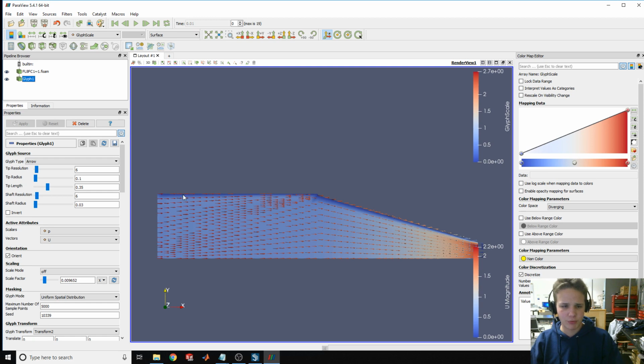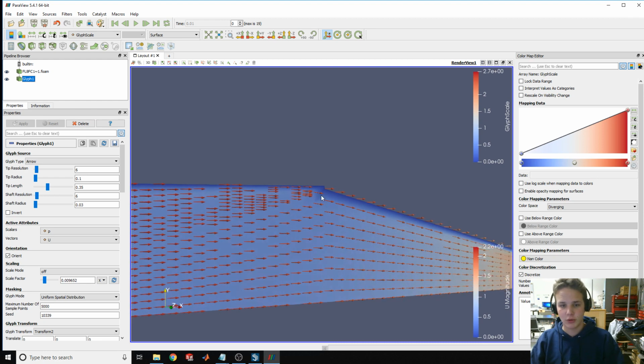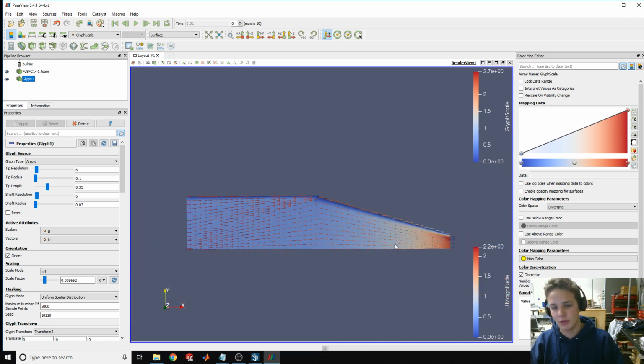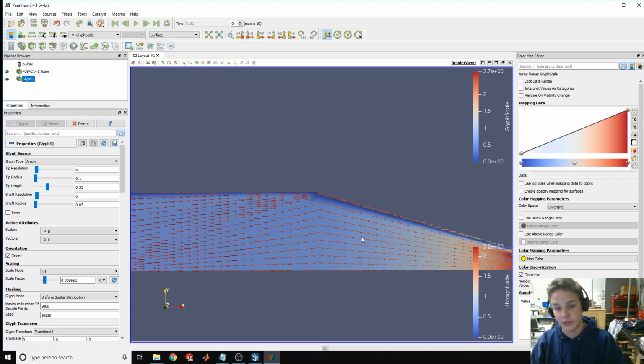You can see that it should be pretty steady here. It should be pretty laminar and just going straight through. But it's actually kind of messing up. And it might be because it's just not a perfect solver or the geometry was kind of weird, but the basic idea is that the flow does contract slowly and it can get faster and faster to the same 2.2 because it's the same ending diameter, so it'll have the same speed as last simulation. But much gradual decrease in cross-sectional area, which leads to a gradual increase in speed.